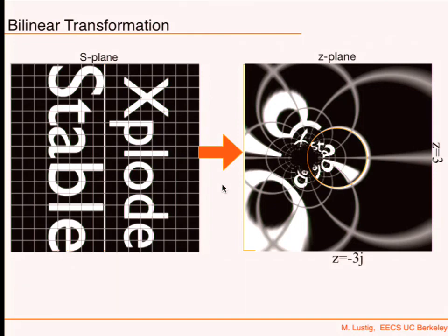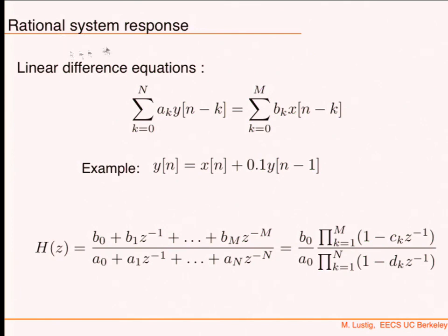Now, when you look at IIRs, or in fact when we represent them, we often represent them as a linear difference equation. So you have some coefficients for past values of whatever output you have. So it's a linear combination of past outputs plus a linear combination of inputs or recent inputs to your system.